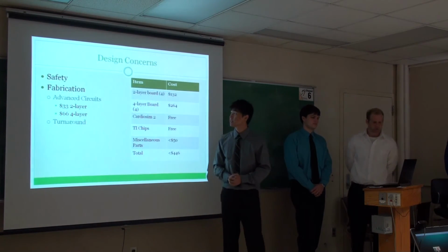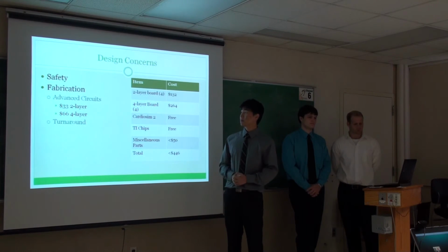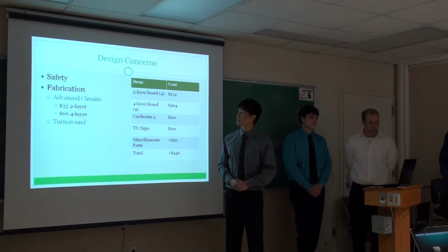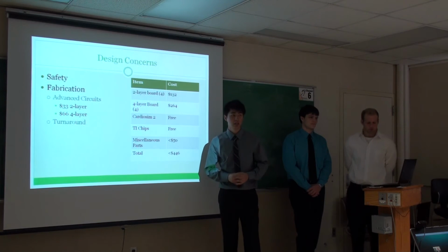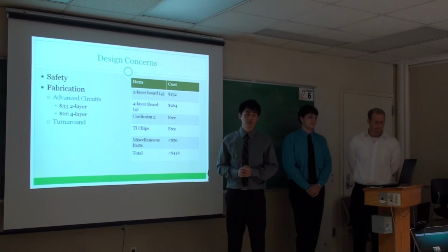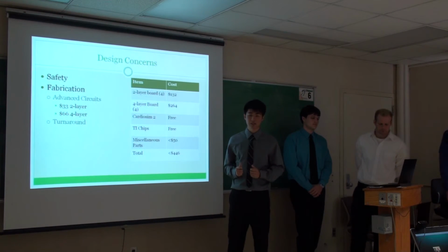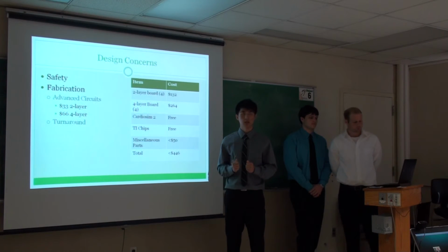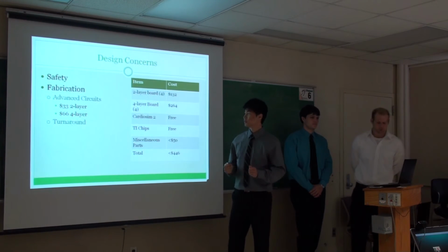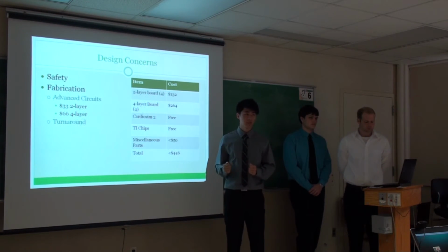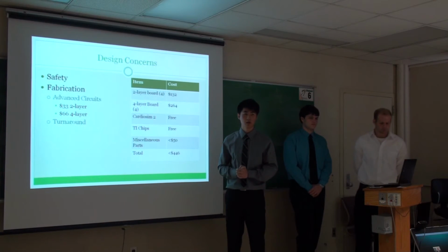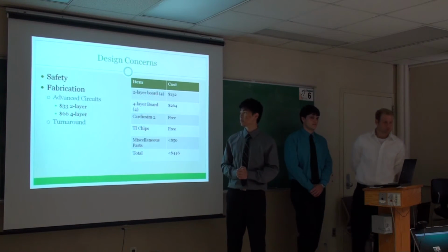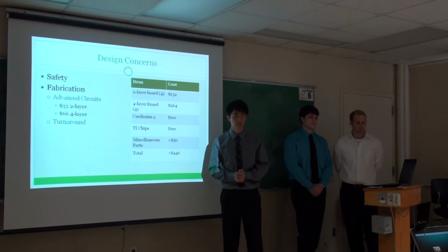After the enhancements, safety and fabrication are the project design concerns. Because the clients or users are directly attached to the ECG boards, we need proper protection circuitry, such as power supply isolation and current limiting resistors.